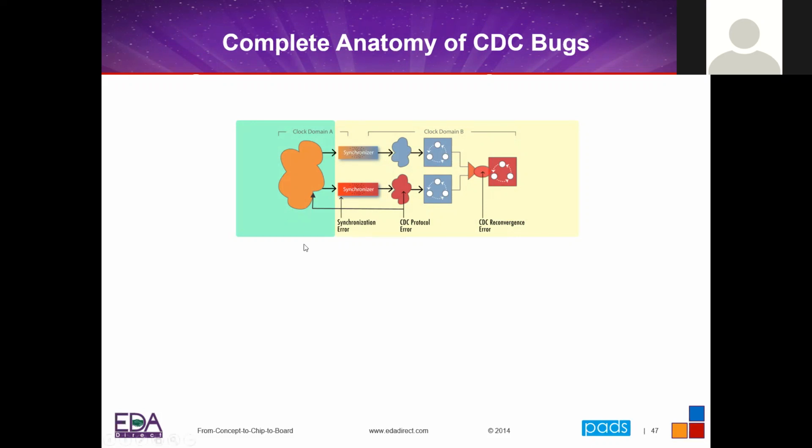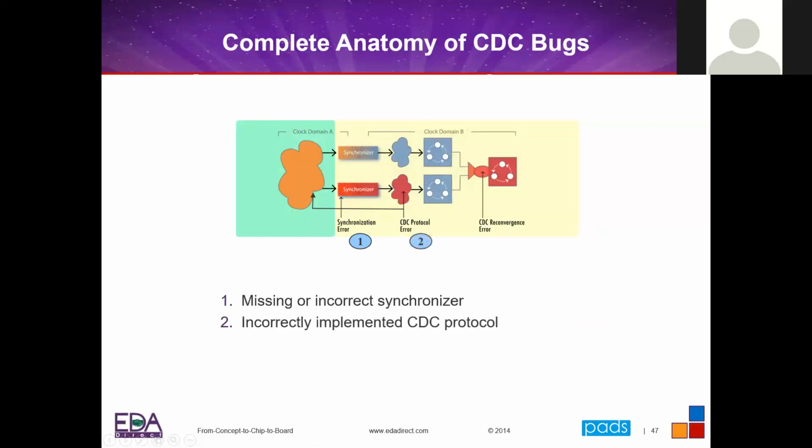So not only do I have, is there a proper synchronizer here? So that's the first thing. Do I have a synchronizer? And is it of the proper type? The second thing is, have I implemented the timing protocol correctly? So can I violate the timing required by this thing?